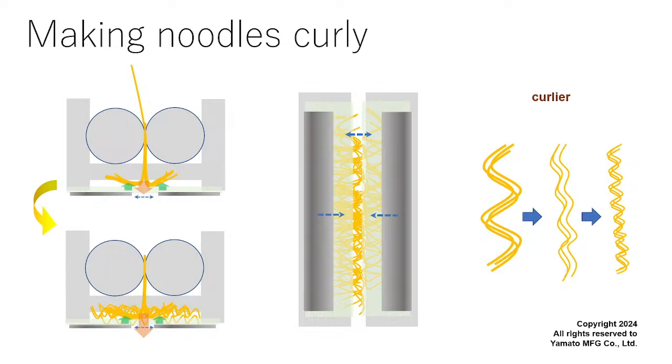There are parts that you can put on the back of the cutter. When the noodles come out, they get stuck between the parts, which are very elastic silicone plate parts. The plates block the noodles from coming out, but as the noodles accumulate inside, it pushes them out. So in the process they get curly.